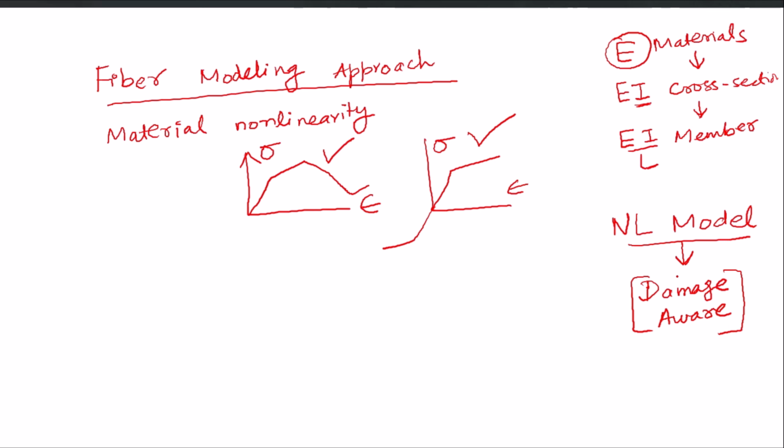And therefore we know that in the performance based seismic design, nonlinear modeling and nonlinear analysis is at the core of that particular approach. So we have to perform nonlinear dynamic analysis in order to check the performance of a particular design at the hazard levels which are higher than the design level.